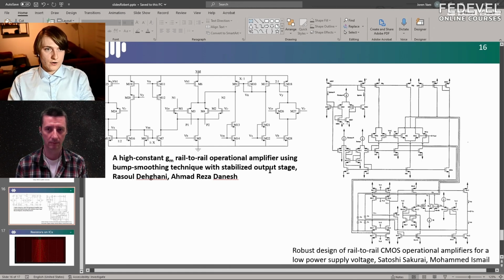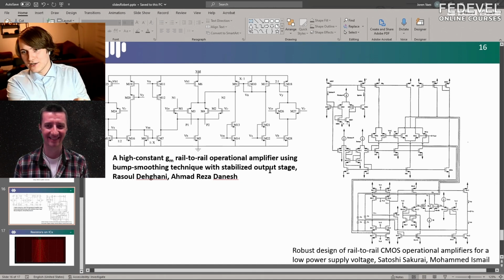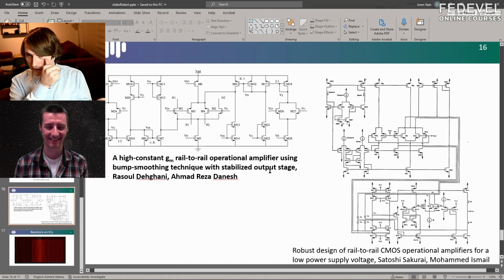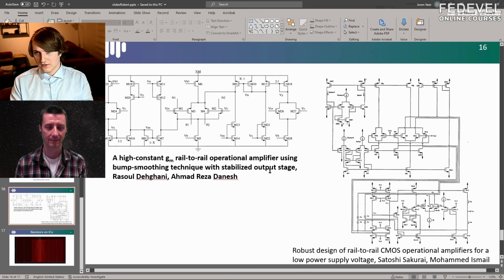That's one option. Another option, which is for instance done sometimes on automotive sensors that I know of, is that they actually have kind of hidden modes. So by providing certain pulse shapes on top of the supply rail, the chip enters a calibration mode, and then suddenly, for example, the analog input, instead of being an analog input, is a digital input, and you can program in the calibration values. And then what you might do is either you just assume that your customer never knows what the key is to get in, and you just leave it at that. But you can also tell the chip itself to blow an internal fuse on the programming array so that it can never be changed. Maybe you don't want, for example, a statistical anomaly to make your temperature sensor enter a programming mode, right? So that's another way.